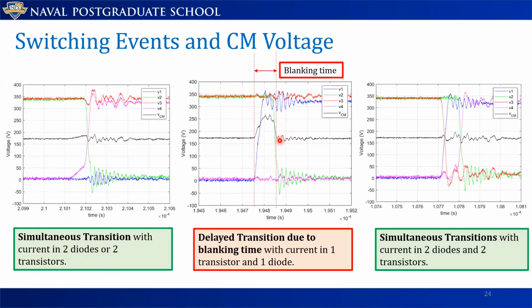Right. Okay. Thank you. So there are a couple of questions about the added 4th leg, which I'll combine. Does the added 4th leg require the same current as the other 3, or can it be lower current rated? That's a very good question. In fact, this was pointed out by my friend, Professor von Juan, last time we met. If the load is balanced, then you don't need to have the 4th leg rated as the other 3 legs. So for a motor drive, for example, you can retrofit an existing 3-phase motor drive with a lower rated 4th leg. And that's one idea that Professor von Juan had last time we discussed, and she was going to probably go and try in her lab. Okay. All right. Thank you.